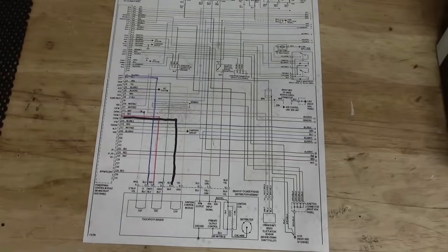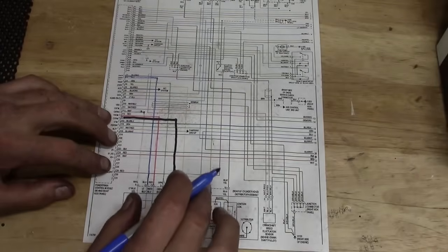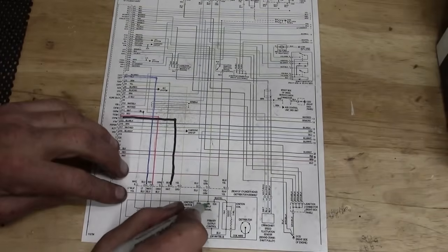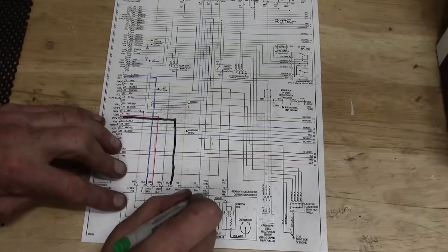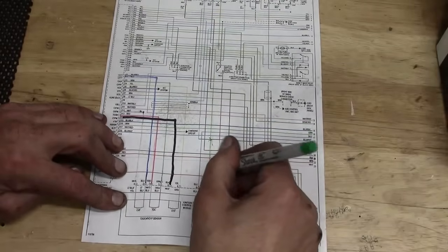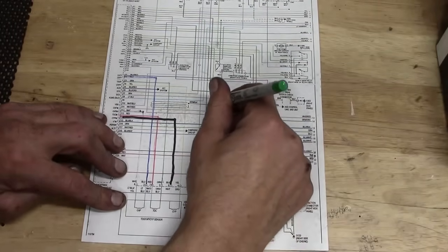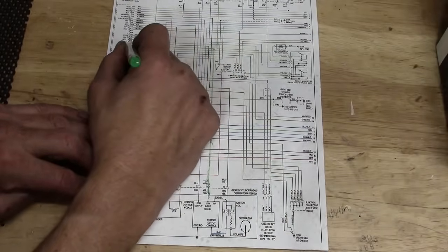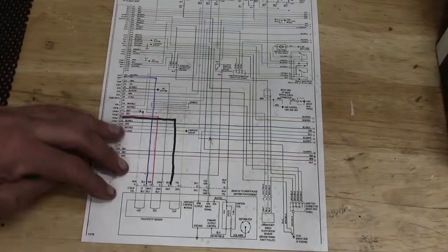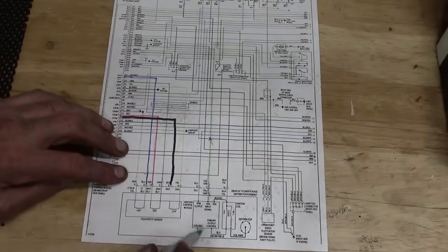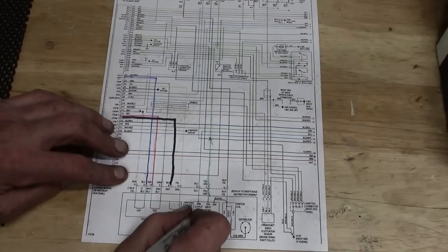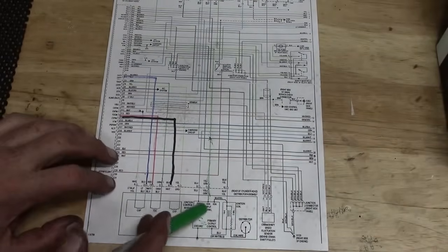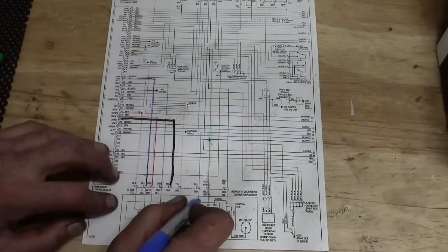One of them is going to be this yellow and green wire. I really like my yellow and green wire. That is important because that is our ignition input signal. So I definitely want to trace him. He should go to the PCM somewhere. So he goes up here, and he does go to the PCM where it says ICM. All right? And that is in the ICM. We see we have the ICM here, the ignition control module. That is part of this assembly. We also have a blue wire coming out, and that is RPM output.